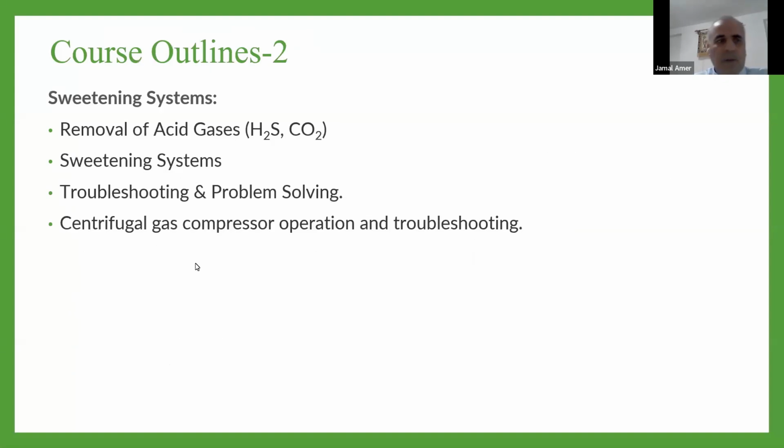treatment. Also, we'll talk in detail about sweetening systems, the removal of acid gases, H2S and CO2. We'll talk about different methods. There are many methods to remove acid gas from the natural gas, so we'll talk about it in detail in the course. We'll also cover different problems and troubleshooting of this facility during operation.